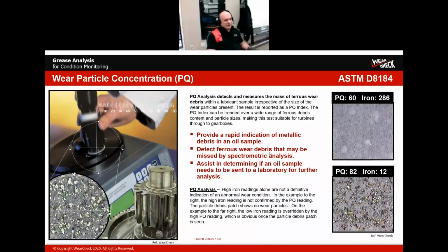The only reason that spectroscopic oil analysis works is because when an abnormal wear mode occurs in a system, it doesn't just produce large abnormal wear particles. It also produces more benign rubbing wear particles that come off. They're very small, anywhere between a few and 10 microns in size, but they increase in quantity when you have an abnormal wear condition.